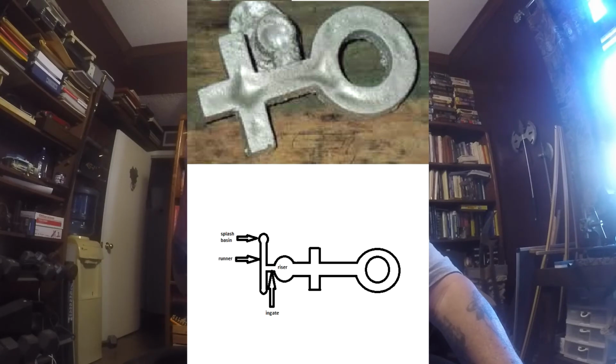Now that might stick to the mold wall in the bottom, but if let's say that's not the case and all you have is dross and good metal, well, the good metal will settle to the bottom, displacing the lighter dross metal, and the dross will generally float to the surface and stick to the mold cavity that represents the surface, the top half of the mold cavity.